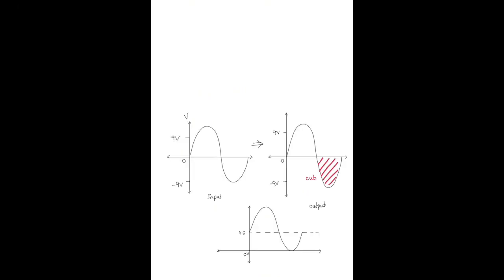As the op-amp is biased in a single supply configuration, the negative side of the sine wave will be cut. But the voltage divider also acts as a level shifter, shifting the entire waveform up. The waveform is shifted up until the midpoint of the sine wave equals 4.5 volts. This ensures that the whole waveform is above the negative edge and the sine wave will be visible.